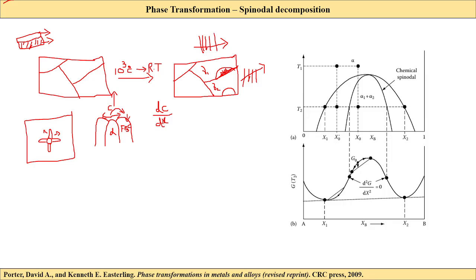So this is one example of diffusional transformation, and there are many examples. I have said there is also the eutectic phase transformation, where liquid will transform into alpha plus Fe3C, and there is also diffusion of carbon atoms at the surface during solidification, right? We even have constitutional solidification, right? It also depends upon how the concentration will change the temperature of the system, the equilibrium temperature of the system, right?